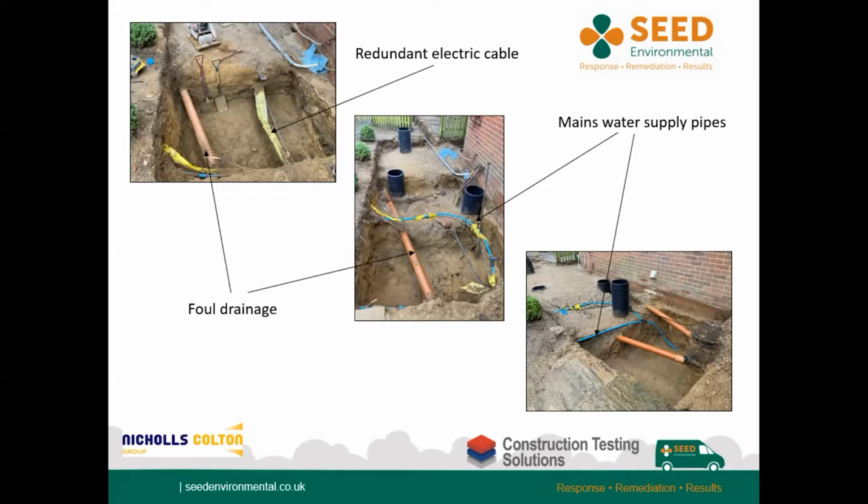and potential remediation. The top left photo on this slide shows the point of loss and completed initial excavation beneath a failed above ground oil supply pipe, as defined during the initial site investigation. During initial remedial works, in addition to the known foul drainage previously identified, a redundant electricity cable and polyethylene drinking water supply pipes were also discovered. This instigated a further phase of site investigations, with samples along these newly identified surfaces confirming significant impact within the